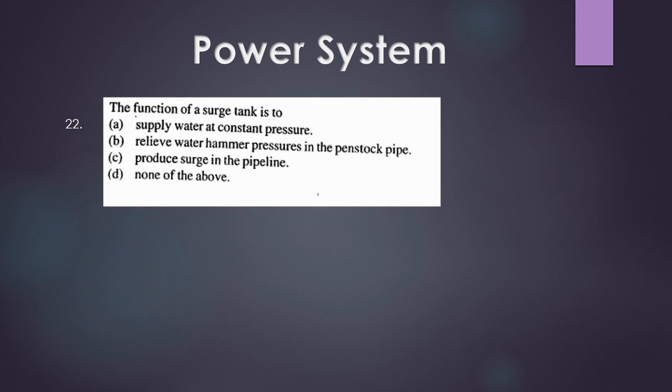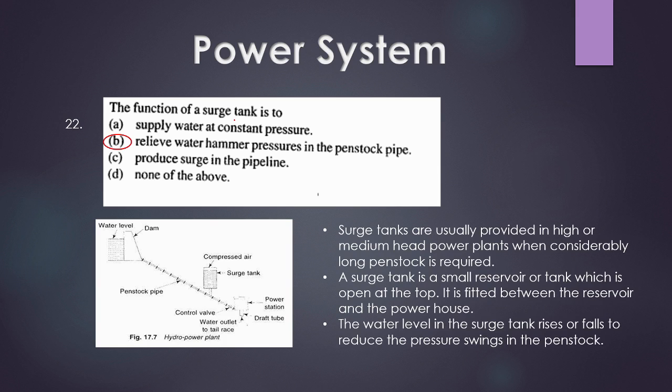Coming to the next question: the function of surge tank is to dash. What is the function of surge tank? Let's see what is the answer. The answer will be to relieve water hammer pressure in the penstock pipe.